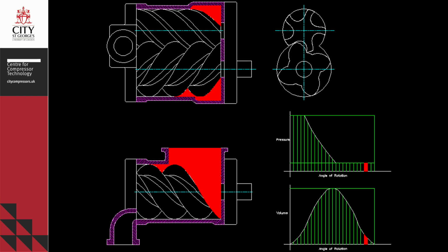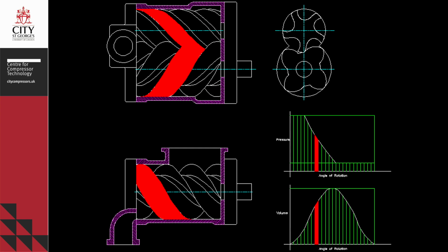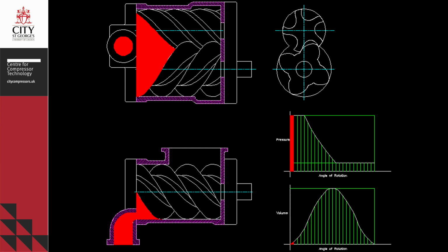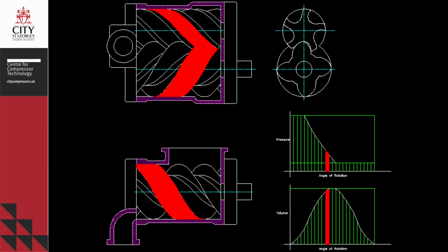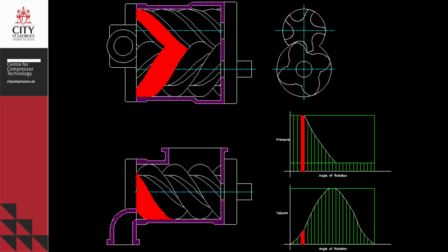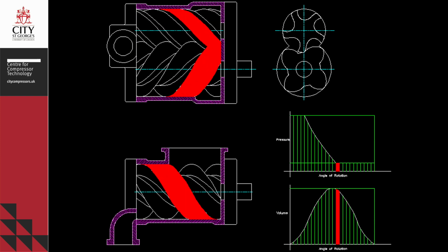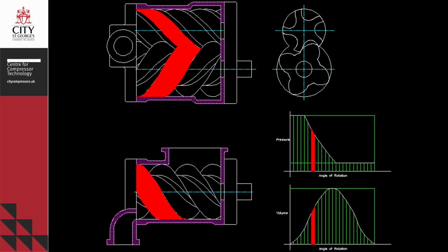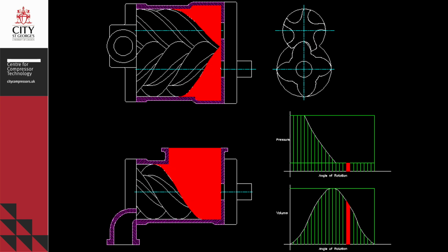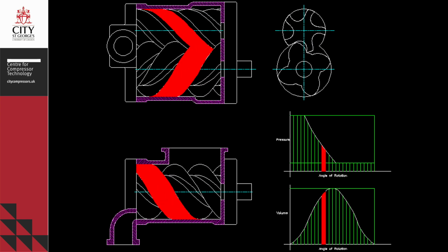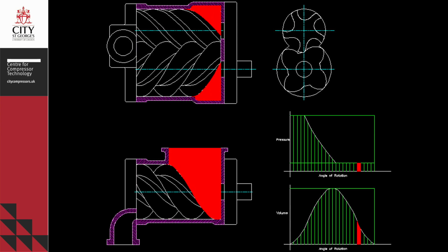The process itself starts with the suction volume, which is now presented in red. Then gas goes through the volume reduction, and after the volume is reduced, it is discharged once the discharge port is open. How this happens, we can see in the volume and pressure diagrams. The lower diagram shows the volume changes when the volume is increasing to its maximum when the suction port is closed. Then it is being reduced, which causes pressure to rise until the discharge port is open, and as a result the pressure will change from the lowest pressure to the highest at its discharge.